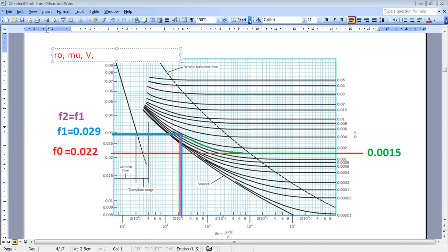We don't have smooth pipes. This is why a new parameter is included, which is epsilon. It represents the roughness of my pipe. So epsilon is another parameter, okay? And the friction losses F, which are induced if you want, by losses when I go over a certain piping system, I will lose energy. So another parameter is F related to major losses.